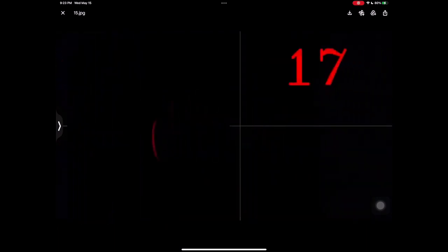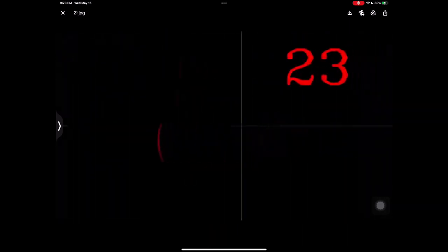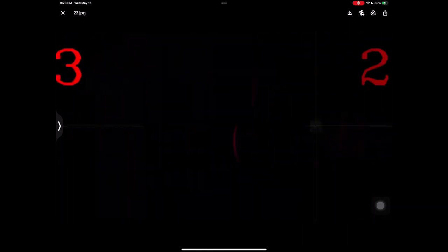So here are some of the images of me calibrating my scanner. The calibration involves taking measurements at set increments away from a solid wall to adjust RPC values and row values within the Python code, ensuring that we are collecting these images at accurate distance measurements for the laser line.